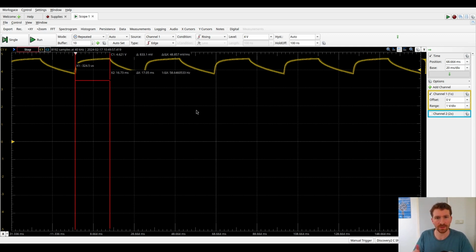I haven't actually looked at the schematic here, but I think there's something going on there. And of course there's another part, which is that the LDR, the light dependent resistor, doesn't respond extremely quickly. So it has a rise and a fall time, which is counted in fractions of a millisecond. So what we can see there is that, yeah, that's going to take some time, but this is actually working really nicely.